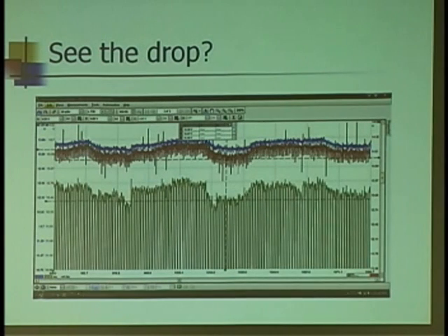Now, when we did our voltage drop testing, we taught guys, if you're new to it, always reference your meter to battery ground. If you're testing on the positive side of the circuit, that means you have to do the math. You have to measure the battery and then measure the power getting to the component. That difference is the drop, right? If you become proficient, then you just move the 1 lead over to the positive side, and now your meter's doing the math for you. Everybody with me on that?